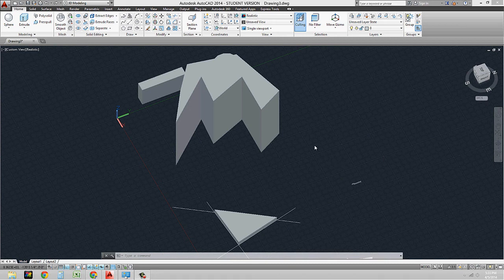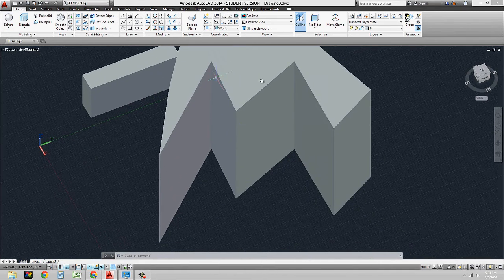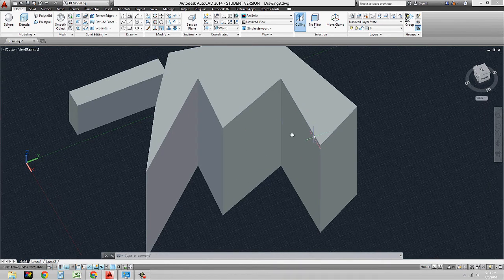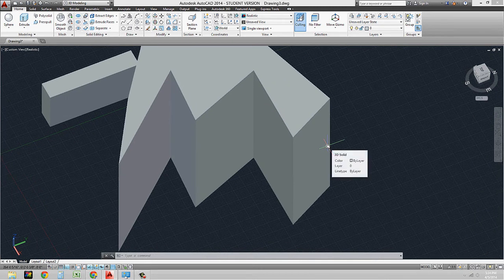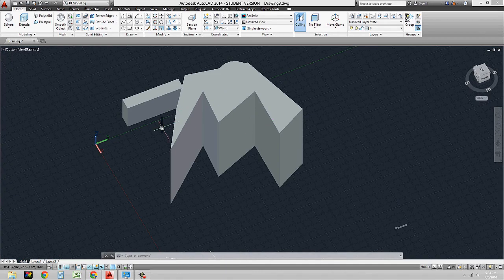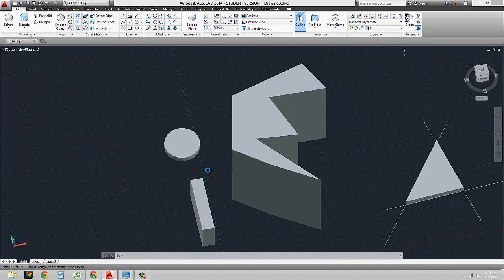One other thing that I want to point out about press pull is that you can do it in some additional ways as well. What you can do is actually draw on existing objects. And you can use the press pull to define windows, to define openings, to extrude some parts of it, and so on and so forth.